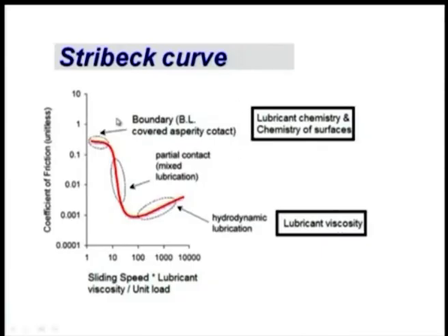When we intentionally do some lubrication on the surfaces, then it will be called a boundary lubrication mechanism. Boundary lubrication mechanism basically is a solid lubrication. A solid form of the lubricant remains intact with the surface. If it is a one molecular thick liquid layer, then it will act as a solid, and it can be called a solid lubricant, it can be called boundary lubrication.